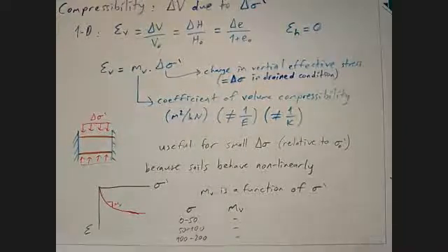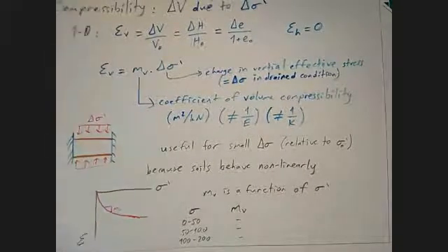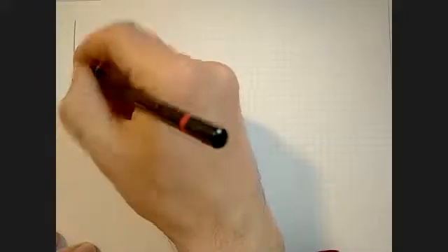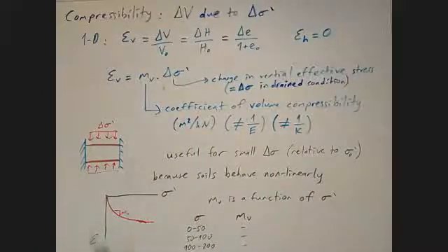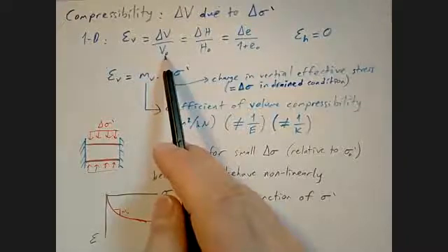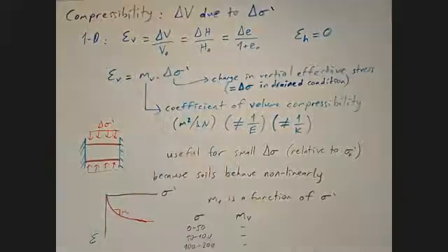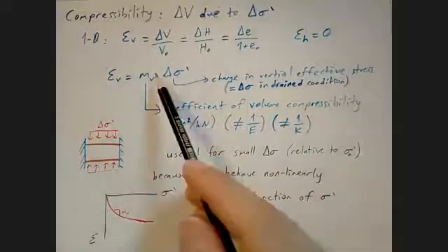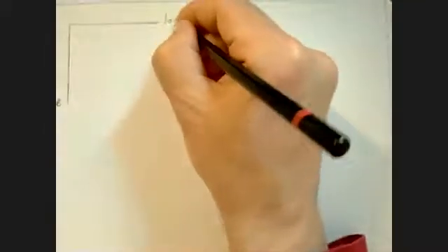So obviously there needs to be a better model than this. And if you have a curved plot like this, you can always try to see what happens if you uncurve it by taking logarithm. And in order to make things more characteristic, because when you say strain, it starts from some volume, and its behavior will change according to where you start from. So instead of that, it is better, in order to characterize it, to plot things in terms of void ratio. So if you plot in terms of void ratio versus logarithm of stress,